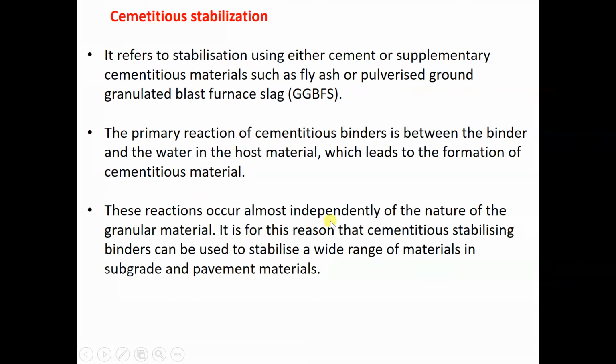This reaction occurs almost independently of the nature of the granular material. The reaction has nothing to do with the parent material, the host material. It is just between water and the cement, or the fly ash, or GGBFS. For this reason, the cementitious stabilizing binder can be used to stabilize a wide range of materials in subgrade and pavement material.